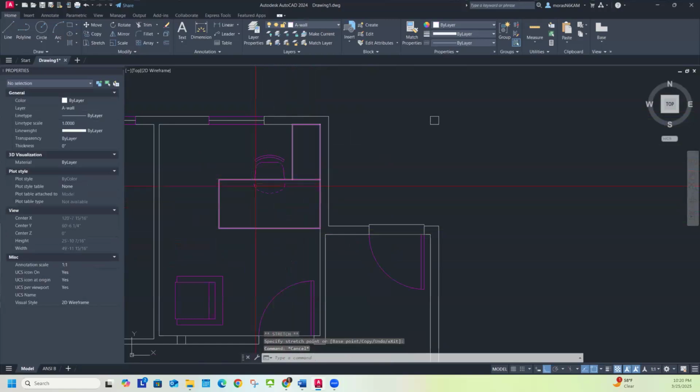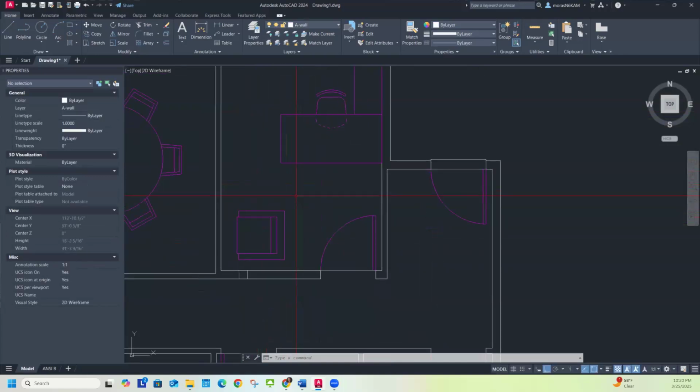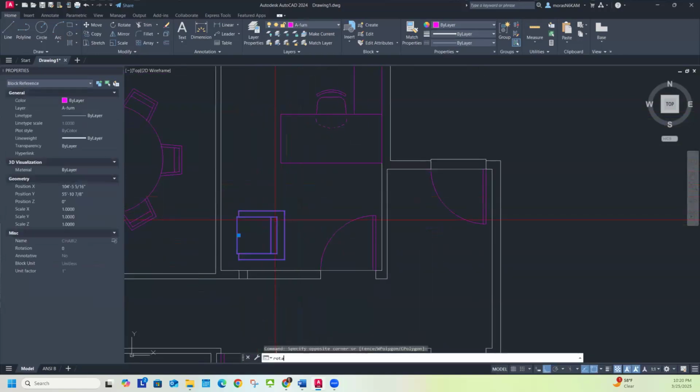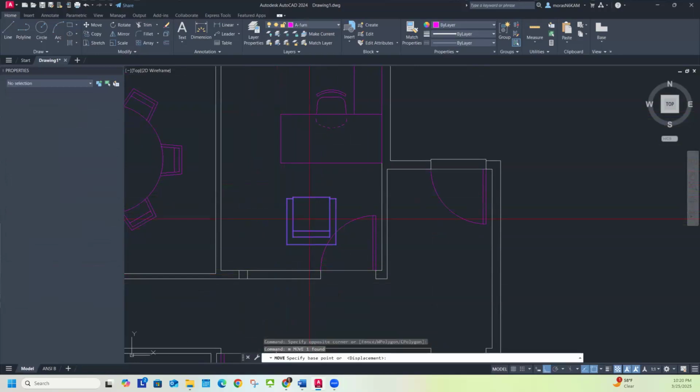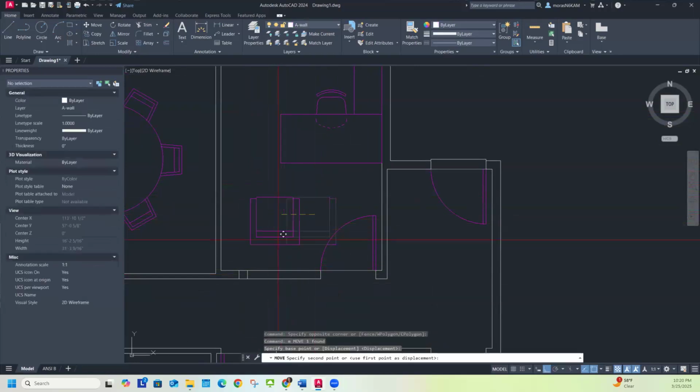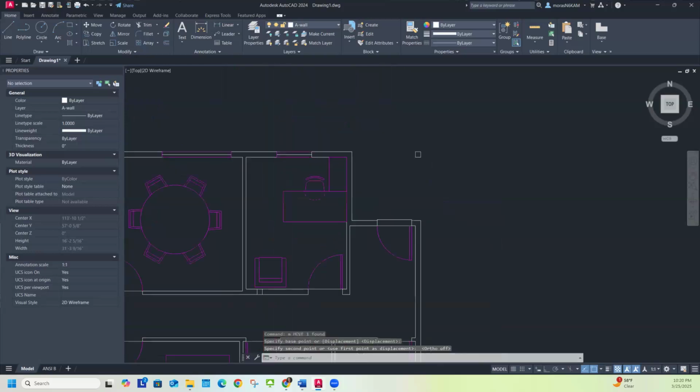There we go. And so this dotted line is because it's underneath the desk. So make sure that is lined up correctly. And I'll rotate that, and then I'm going to move that over to, I could turn off this ortho mode. Move it to right about there.